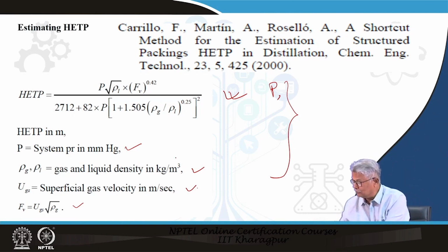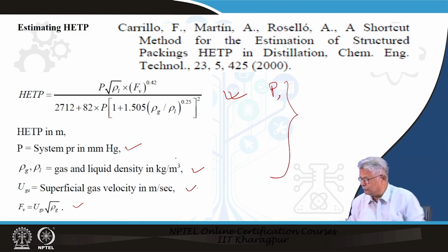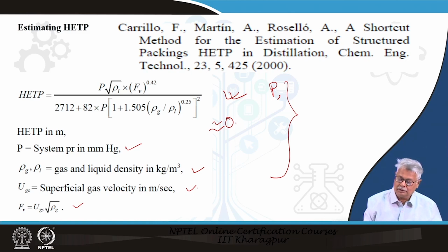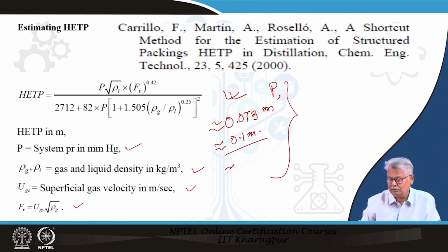I have already calculated this using this particular data here, and we get a very small value of HETP, and this comes typically close to around 0.073 meters, say 0.1 meter, which makes it around 10 centimeters.